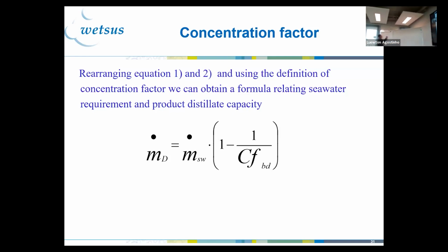Which means 10 to the power of 5 people. And in general, a person drinks or uses how much? One person uses more or less 100 liters. Let's just make our life easier: 100 liters per day, right?